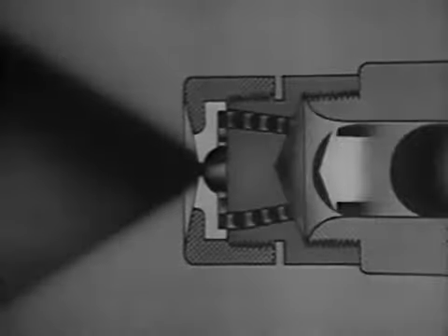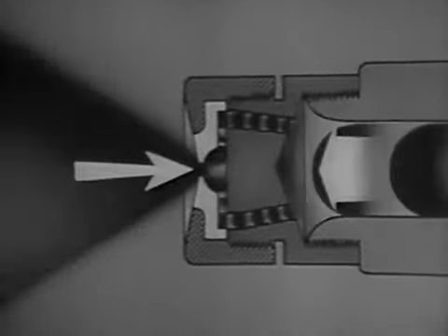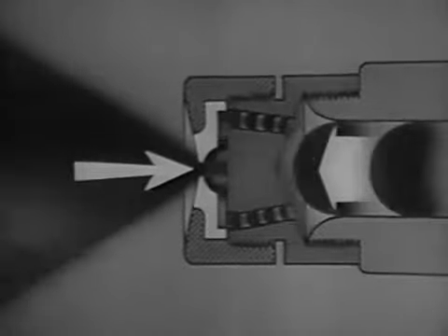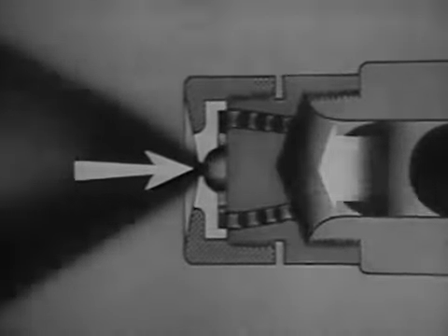However, when you want an increase in the firing rate, the sprayer plate in use at the time may have too small a capacity, that is, too small an opening to provide the necessary quantity of oil, even with oil pressure at maximum. You must substitute a plate with a larger capacity. When you want a decreased firing rate, the sprayer plate's capacity may be too large to properly atomize the reduced quantity of oil. You must substitute a plate with a smaller capacity. Frequent changes are necessary because the operating range of a given sprayer plate is very limited.